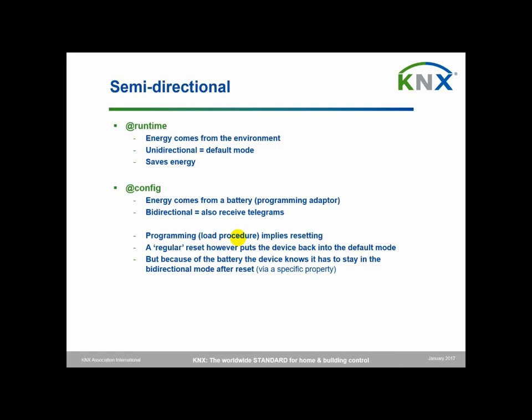There's also one extra aspect: programming as such, so performing a load procedure, implies resetting. Because of the battery, the device knows that such a reset during this load procedure is not a regular reset, because a regular reset will always put the device back into the default mode, which is unidirectional.